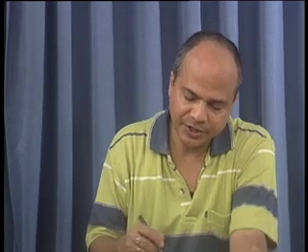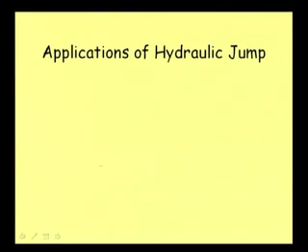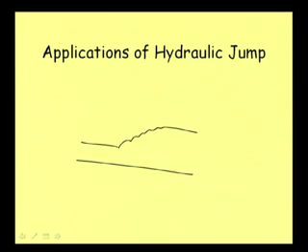So, for mixing fertilizer or any chemical in any water distribution system, if we can have a hydraulic jump, there we will have turbulence, and at that portion we can mix the chemical. Say in an irrigation canal, if we have a system of forming a hydraulic jump, normally the flow is moving at this level as a very simple flow, and if we mix chemical here,